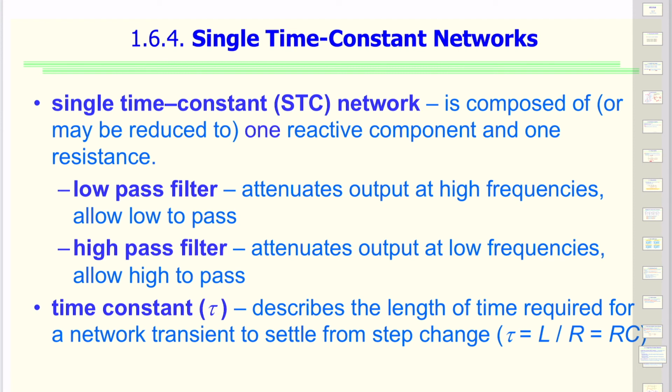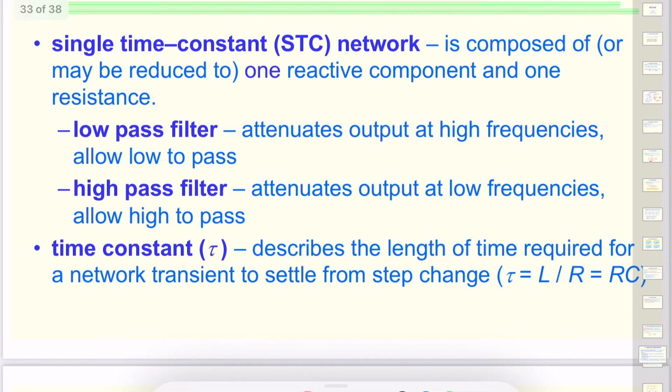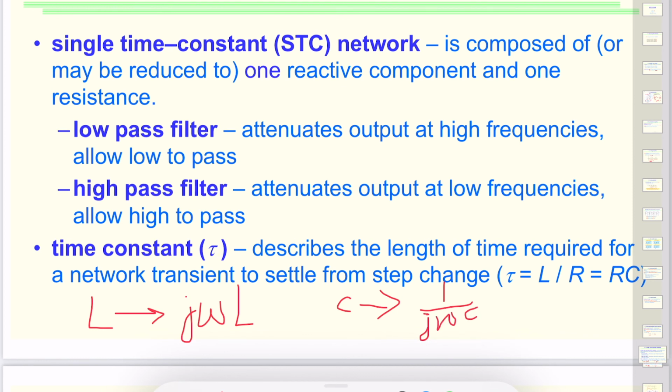So an inductance L has a reactance or impedance that's written as j omega L. So for an inductor, I would use its reactance as j omega L, and for a capacitor, I would use 1 over j omega C. Which means now the reactance is a resistance, but it's coming from these components which have a frequency response. So we call them reactance. They have a dependence on the frequency.